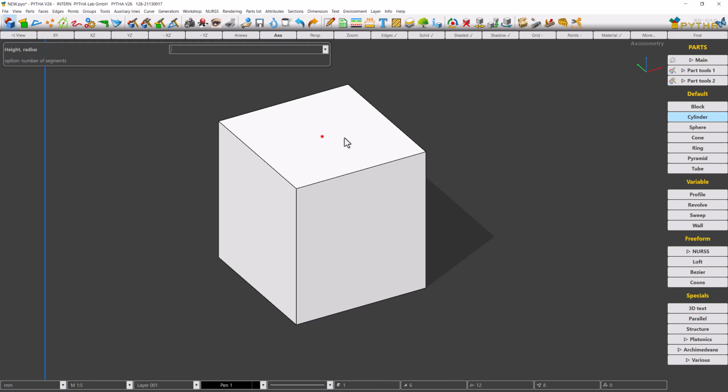If you want to pick the center of faces, solid mode must be activated here at the top. Otherwise, the mouse click will fall through the face and you will pick geometry that is located behind the face. Always make sure that the mouse cursor shows the desired element.